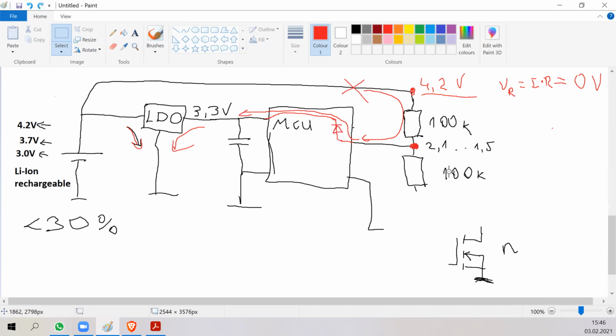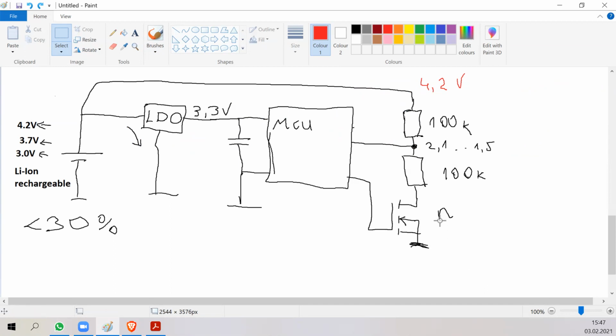So it's not such a great idea to remove these electrostatic discharge diodes, but they do bother you when you connect a higher voltage through a resistor and you don't notice it, right? So you're absolutely correct that you need to put the transistor on the top side. So let's try to do that. And let's try to do it correctly, okay? So instead of connecting it to the bottom part, let's connect a P-channel MOSFET on the top part.